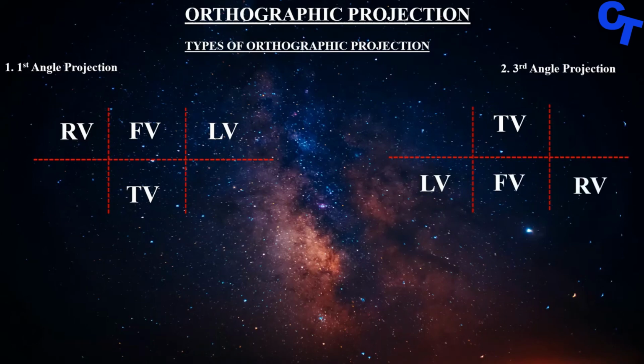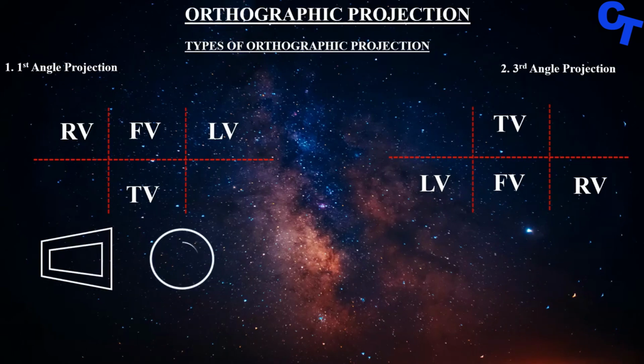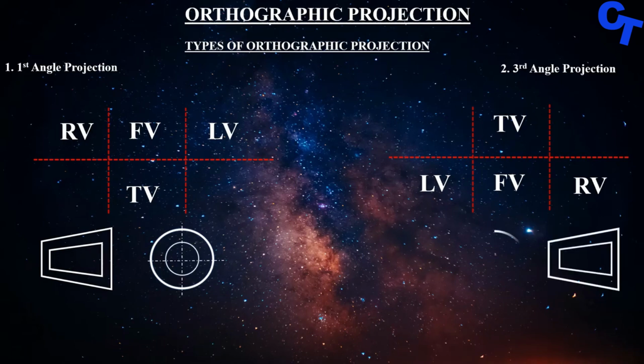But in some cases you may not be told to use first angle orthographic projection in a sentence. They may show you this sign. This is the symbol for first angle orthographic projection. You can see we have the cone and the circle. Since this is engineering drawing, each and every time we draw a circle, we should not forget the center line. On the third angle projection symbol, we start with the circle and then have the cone, and since it's engineering drawing, we put the center lines.